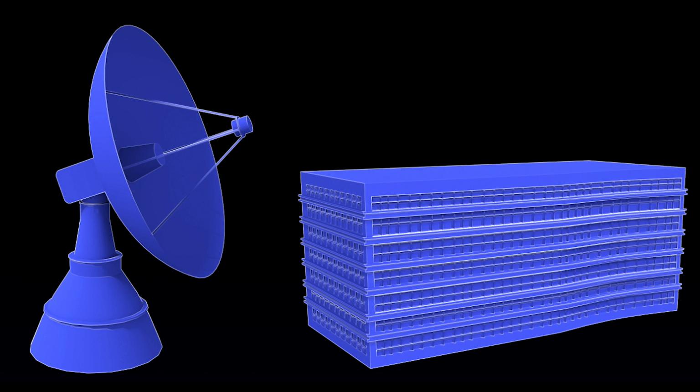Ground stations will send commands via the S band, which is 2 GHz radio signals, at speeds of up to 32 kilobits per second. It will also receive science data at the Ka band, which is 26 GHz, at speeds of up to 500 megabits per second, and engineering data at S band up to 680 kilobits per second. Using multiple contacts for several hours from each station, 1.4 terabytes of science data will be downlinked from the observatory each day,